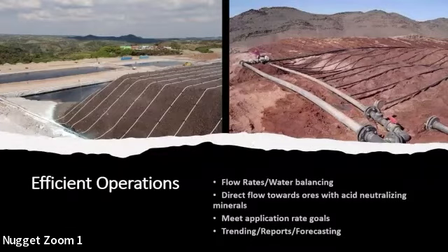I'll just ask a quick one. You spoke about modeling down to 60 feet below, so 3 or 4 lifts. You said it's possible up to 80. Is there a way you could manufacture the compaction test and simulate a depth like 200 or 300 feet? I'll repeat it for people who are online: they're asking if there is a way to modify the testing apparatus to be able to go to deeper depths beyond 80 feet.